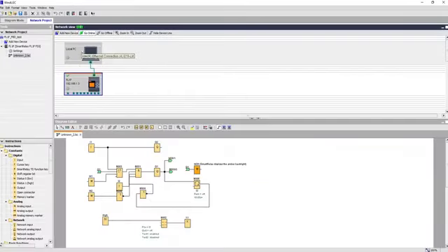In this software, I've already done some small programming. I have taken two inputs, I1 and I2. It's a simple motor start and stop operation. And I've taken a timer just to make sure we get the values in the web editor as well. On the bottom side, I've considered a text display, which is displayed on the built-in module of FL1F.